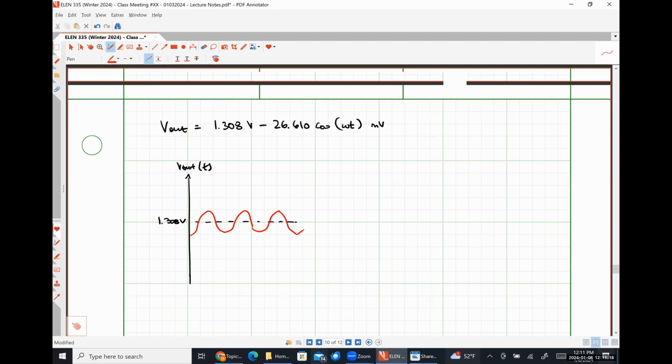So we have achieved amplification. The reason why I'm pointing it out is because one of the most common misconception type things that I see is that we forget that this AC signal is actually superimposed on top of the DC operating point of the output.